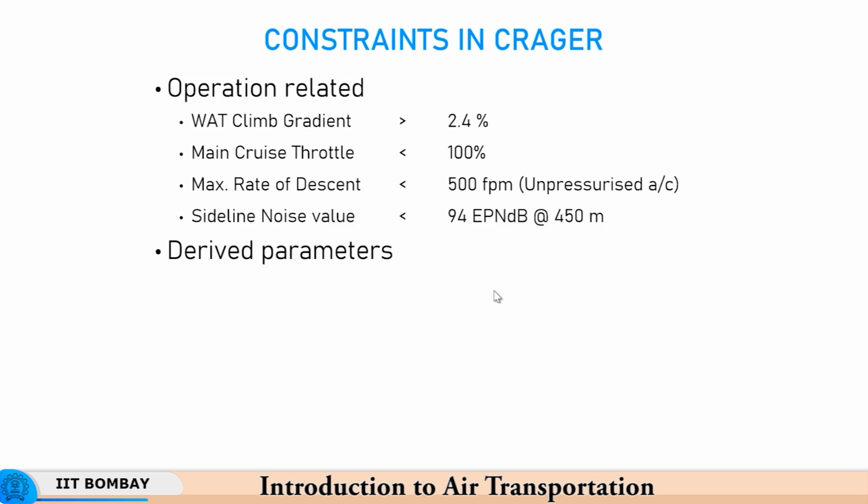Then there are some derived parameters. Remember, we had some parameters in the design variables which were actually not supposed to be there, they were supposed to be calculated. So, what we do is we use the power of optimization in meeting certain constraints by ensuring that some derived parameters meet the requirement of the actual. So, for instance, there is a very important consideration for transport aircraft from the safety point of view, and that is the static margin.